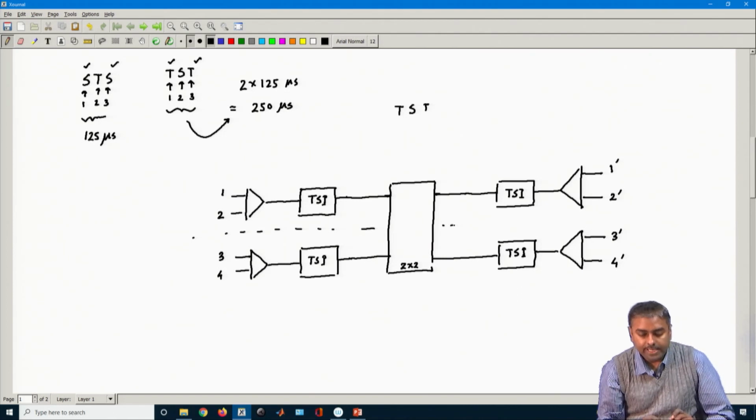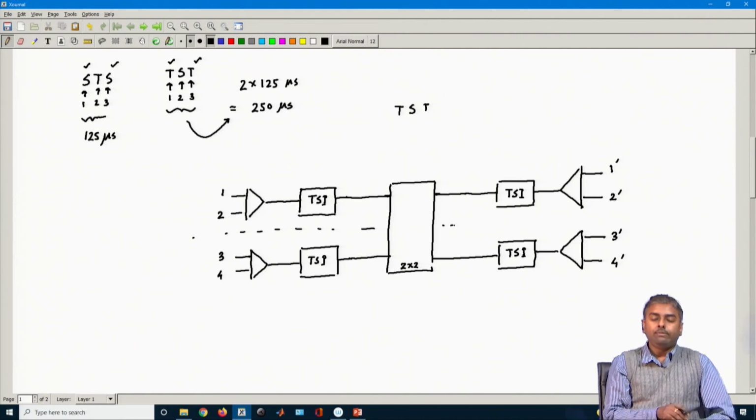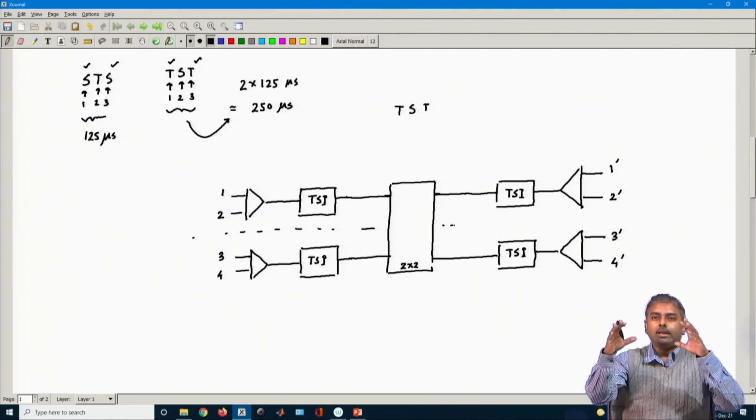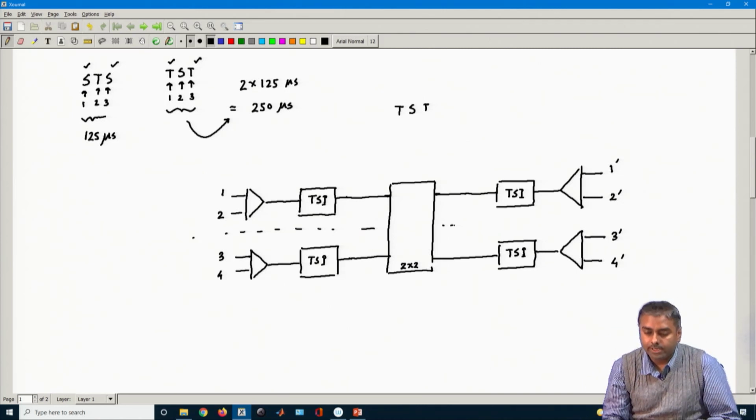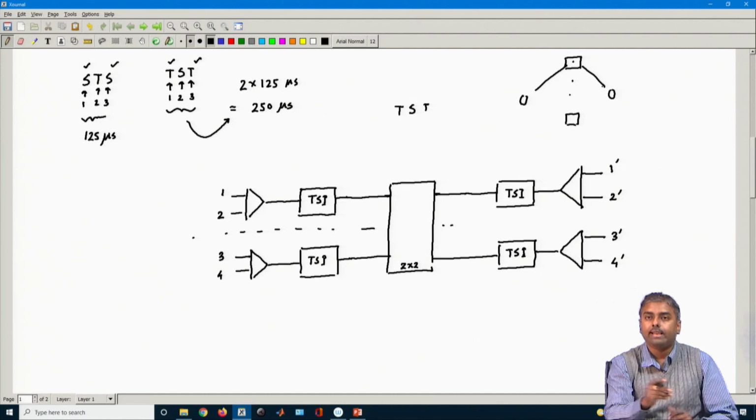Okay. So, now let us try to give connectivity, and see whether the blocking condition comes into the picture. So, when we talk about this blocking, if you remember the Clos argument, you had something over here, in the middle there were some k stages, and each of these stages was getting shared among the input and output.